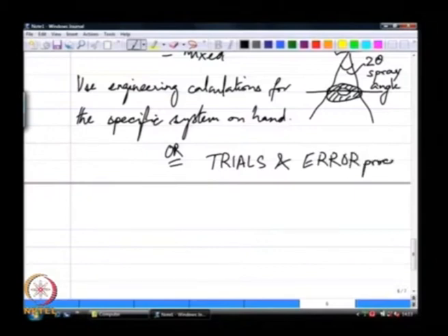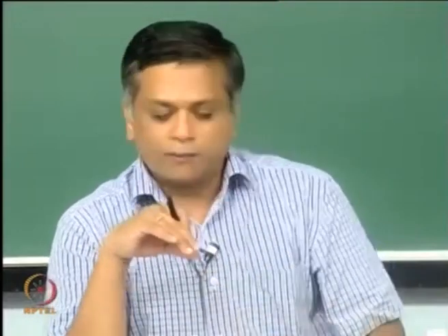process. So, you try out all the 3 or 4 different nozzles, you basically whittle down from a catalog of a few thousand nozzles down to about 3 or 4. So, your best bet may just be to try out all 3 or 4 and see which one gives you the best performance. But if the trial process is expensive, like maybe in some cases, you may need to go through some calculations to really come down to one nozzle as your specification.